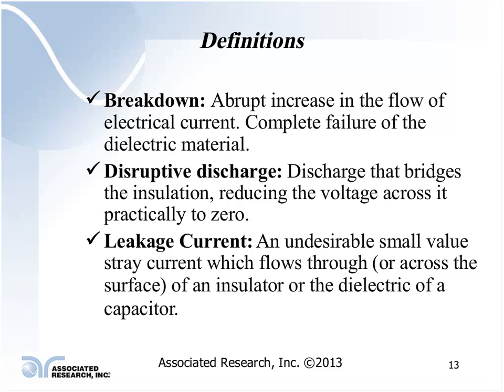It's going to have a certain amount of leakage current depending upon the capacitance of the circuit, the applied voltage, the frequency of the applied voltage. All these things are variables that can change how much leakage current is actually flowing through your product itself.